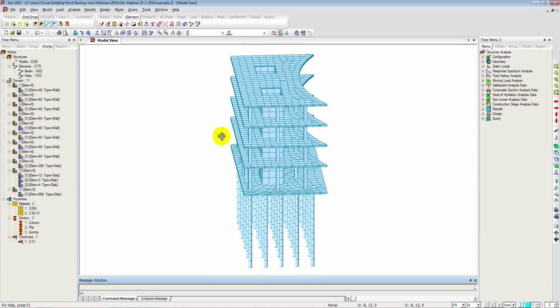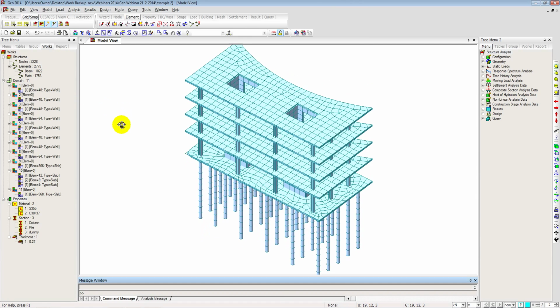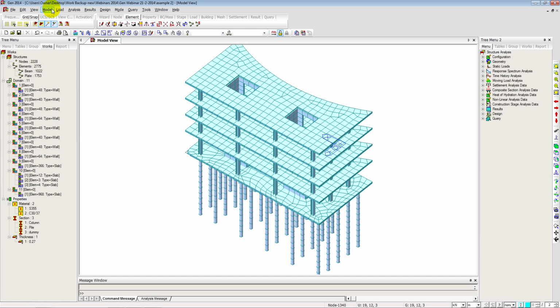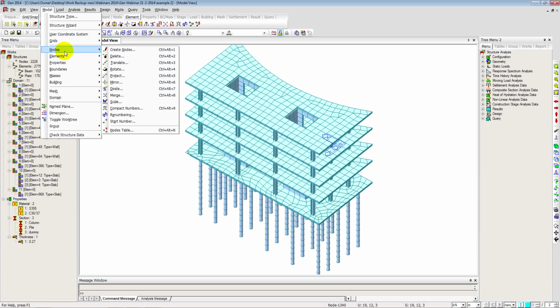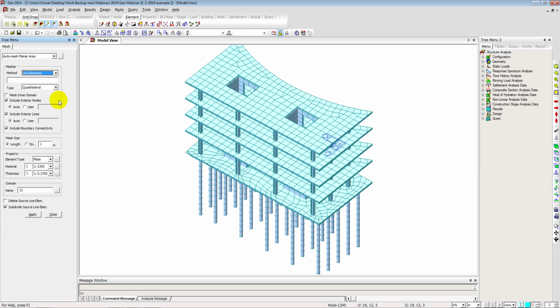Okay. So just swivel this around quickly and do the back of the building. To create a retaining structure, just use the mesh by nodes. See there, we just select the nodes. Select the 4 points around the outside, go all the way to the end, and click apply.